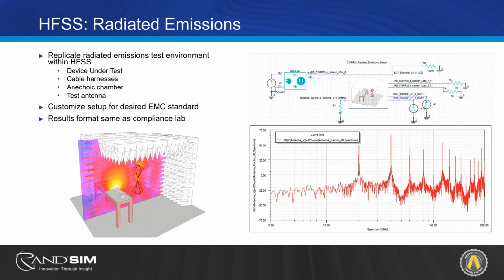But from a general design workflow method, I would suggest that you stay primarily within the EMI SIwave tool. That's just because of the amount of value and answers and quickness; it's much more intuitive to your workflow to use the EMI scanner workflow during your design phase than this. This is sort of at the end. You could do this if you wanted to check, but like I mentioned, sometimes if you don't have a computationally powerful machine, these simulations can take a considerable amount of time. So it's something to consider, but it is a neat feature that is existing within the tool set.